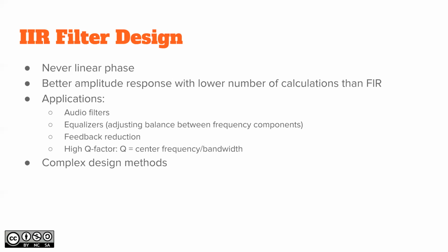But on the other hand, if you are using post-processing, then you can always turn the non-linear phase response into a zero phase response by a trick. I showed that trick already on the responses. So that was the zero phase shift.